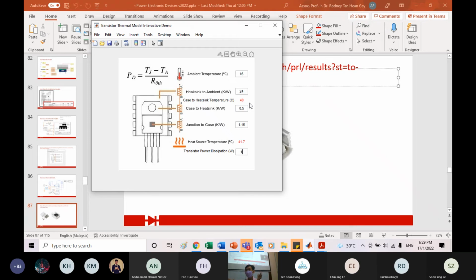I believe in the past you all didn't care. You know that there's a problem, but you don't care. So now I move you another step further. All the time you look at the heat sink, but you have no idea what this heat sink is about. It actually gives you a thermal resistance. Ask the shop, or if you know how to read the data sheet, read the thermal resistance. Get the transistor you want to use, model it in MATLAB, and make sure that the transistor doesn't shoot up until it's so hot that you burn your hand or whatever.